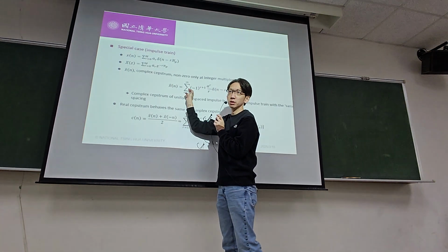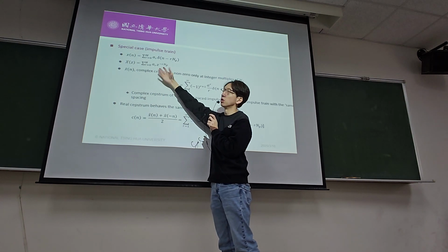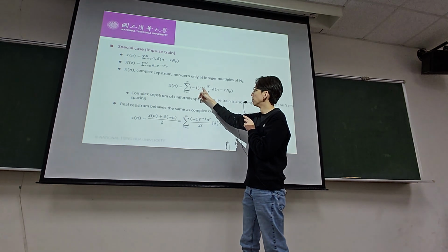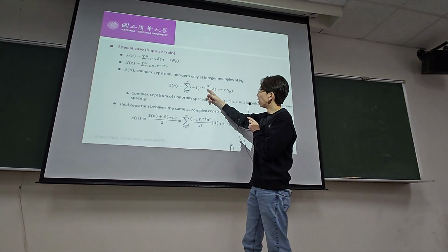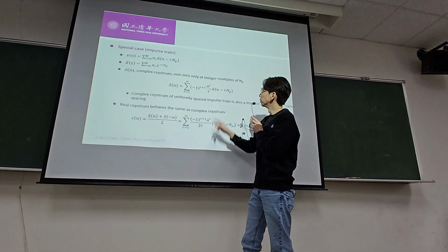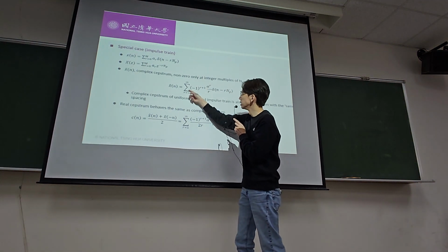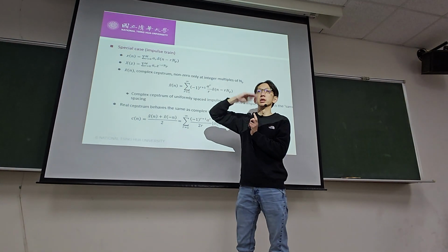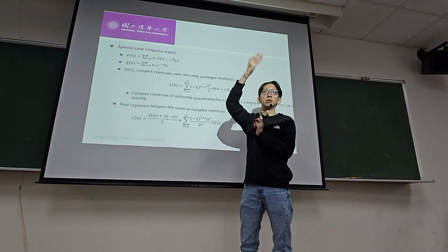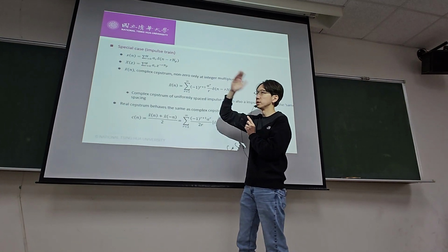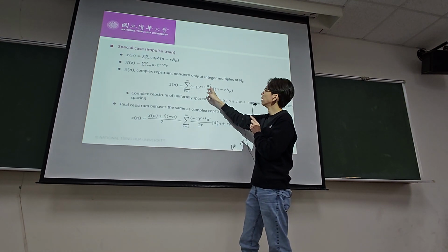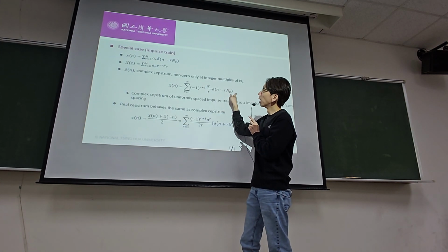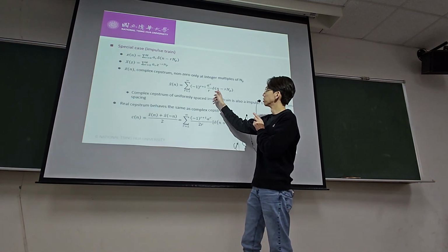Okay, try to do this derivation. Basically what you need to do is take the z inverse of the log of that. You'll see that it equals the sum over r of minus 1 to the r plus 1, alpha to the r divided by r, again with the same delta of n minus r times np. So you can think about this as a decaying, oscillating sequence, right? Because it's minus 1 to the first order, second order, third order, fourth order, so it's basically oscillating signs. This is your magnitude divided by that oscillation index. Then you multiply by a delta function that's also an impulse train.